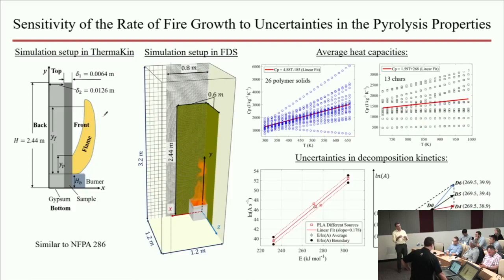So there you have, for example, if you look at the critical heat flux to ignite a table of wood, it's on the order of 10 kilowatt per meter square, roughly speaking. Now, if you take the same table and reduce it to a small sample that is a 1 millimeter cylinder, then it's going to be 30 kilowatt per meter square. So it's not the same. Okay, it's not the same problem. And that's due to the change in convective heat transfer.